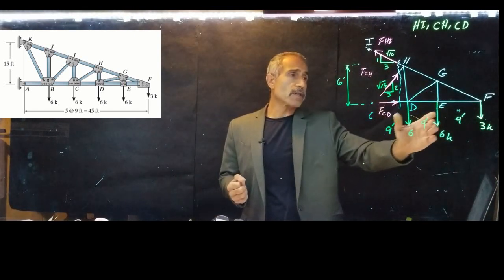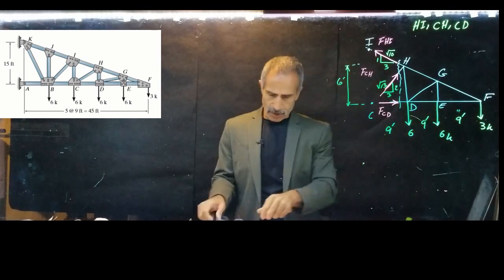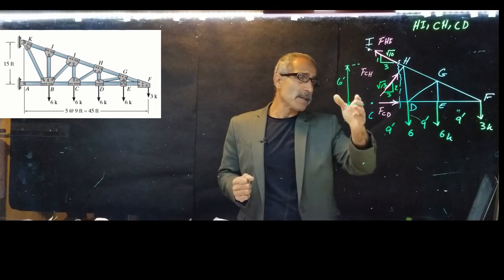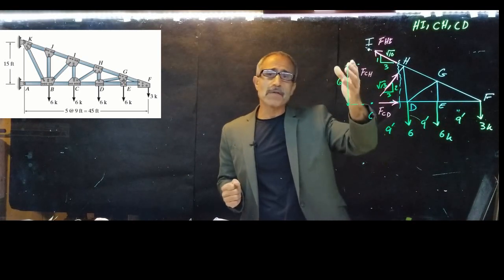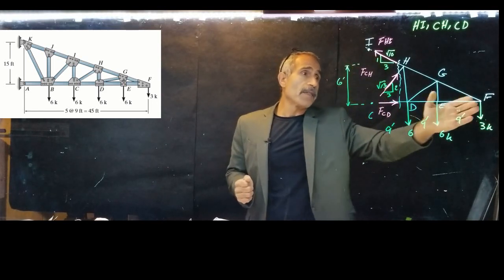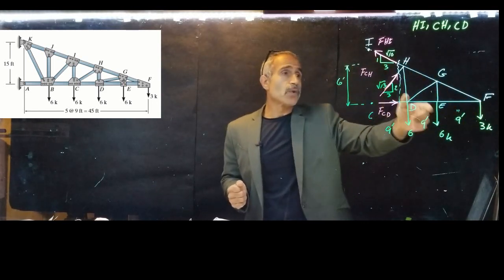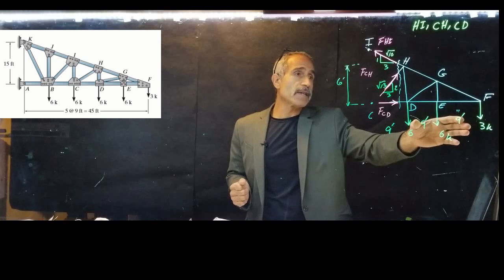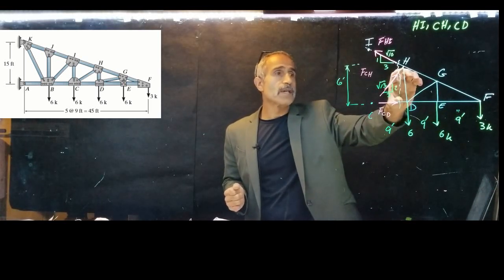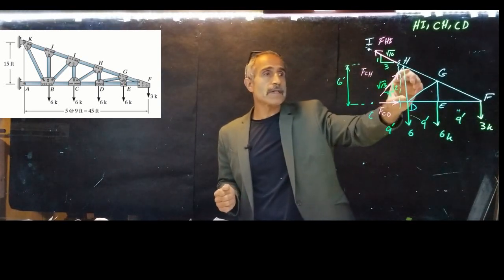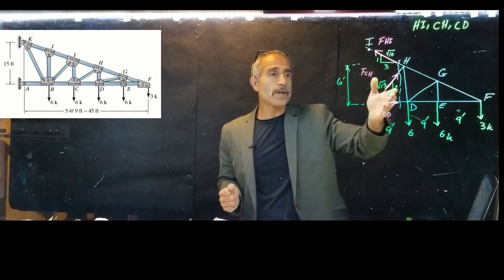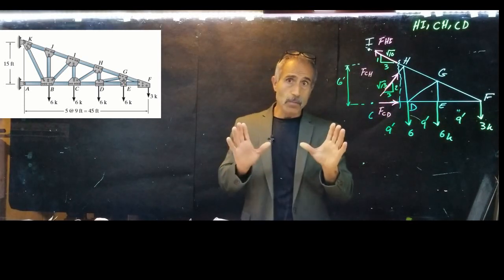When we look at this truss, it's 45 by 15. So 45 divided by 15 is 3, so we know this angle has a pitch of 1 to 3. And because now you know the pitch of this line, where you make your cut, I'm going to have 18, and 18 divided by 3 will give me 6. So if I have a 6 here, then I have 6 going this way, and 9 going this way. So the pitch of this line is going to become 2 and 3, and you can figure it out. That's the most important thing.